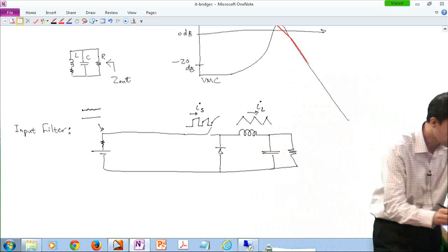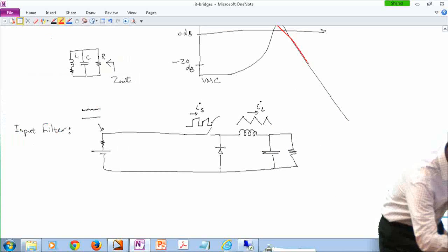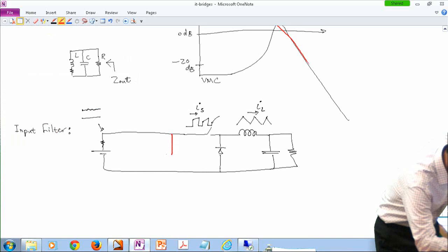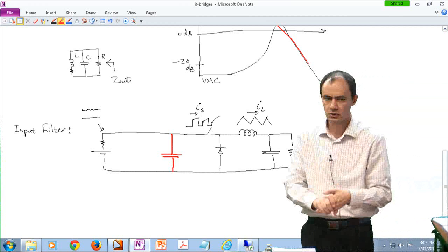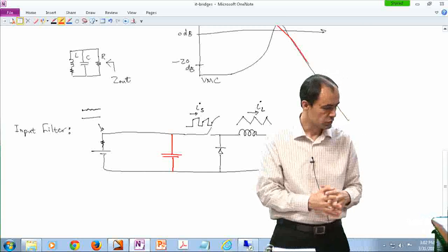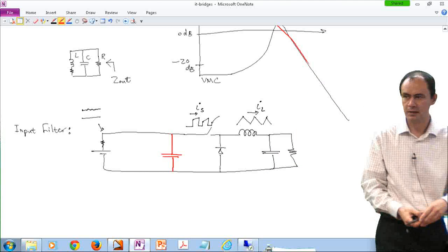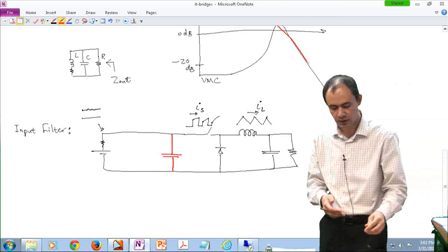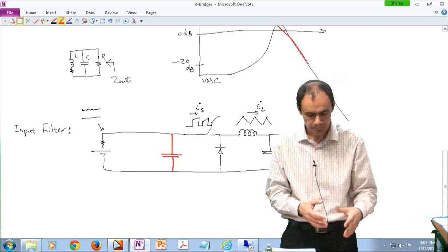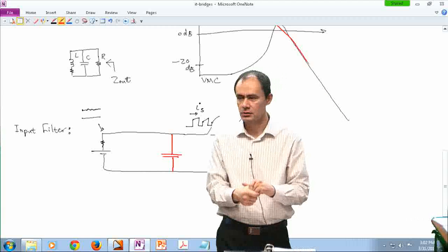So you may say, no problem. All we got to do is place a filter between the source and the load. For instance, the simplest filter would be just a capacitor. So you put the capacitor as close as possible to your source. And sometimes putting the capacitor is actually quite normal. You are not going to face any problems in terms of stability. And this happens a lot when you're dealing with solar panels, okay?